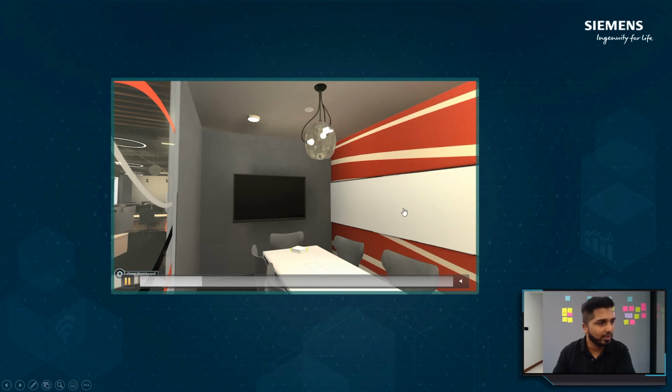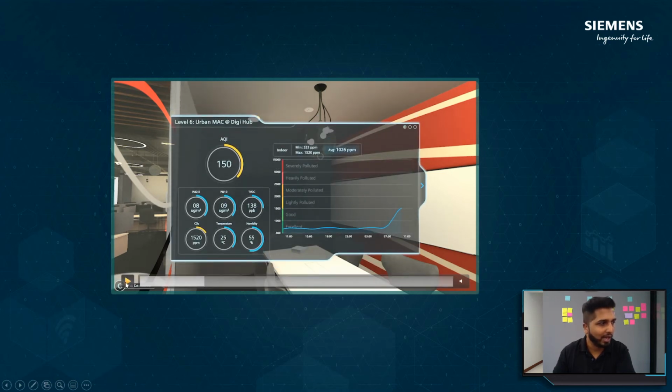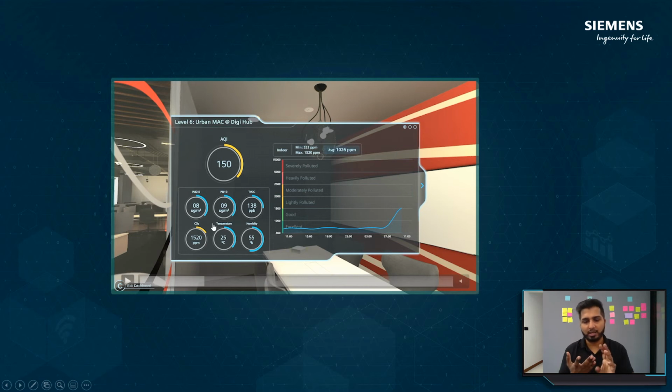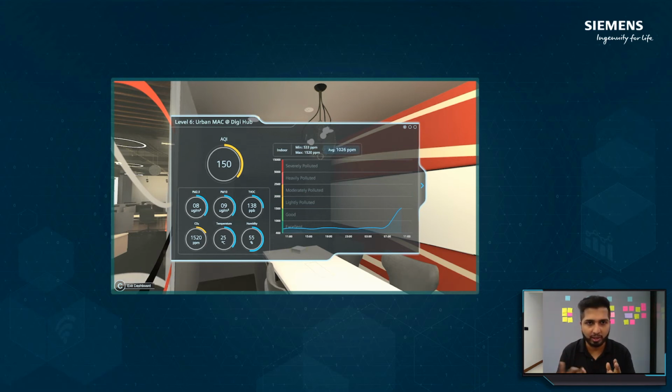Once you open the sensors, it will tell what the actual issue is. Yes, air quality is poor, but there are various factors for that. In this case, it says the CO2 is higher in this area. So he can narrow down to only three causes for CO2 to be higher. Further, he still has to investigate whether it happened previously or not.